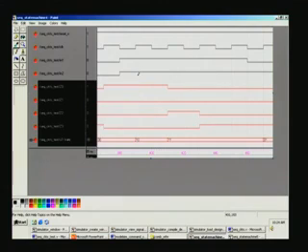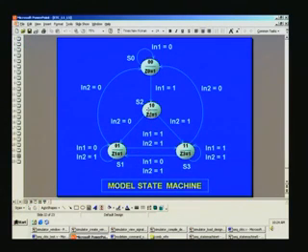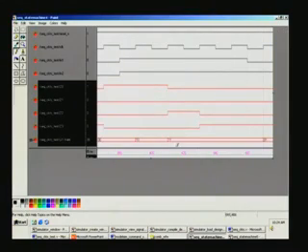In S2 state, both inputs are 1 here. So, where should we go? Both are 1, right. So, it is going to S3 state. That is what is happening here, and continues to remain in S3 state so long as the inputs are same, and in fact it is same right up to this, and then finally it goes to 0 1 here. So, that is for 0 1 transition. So, let us see that.